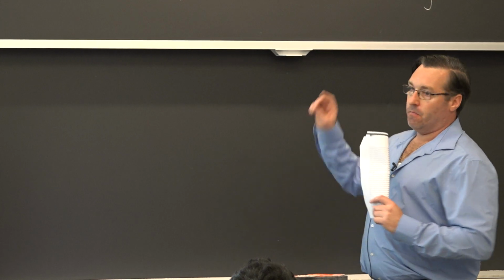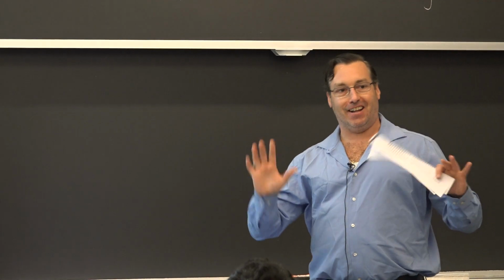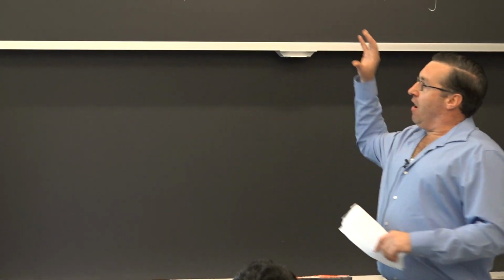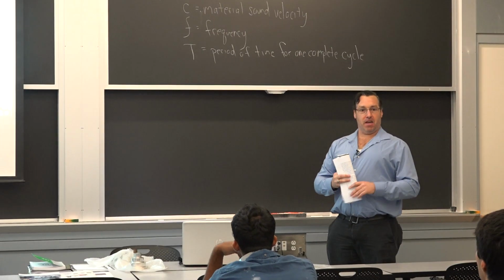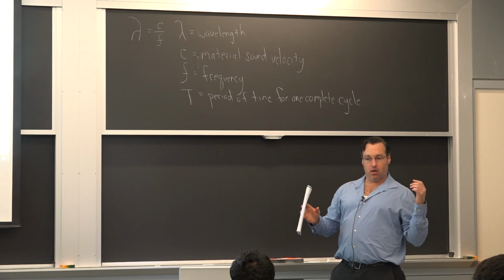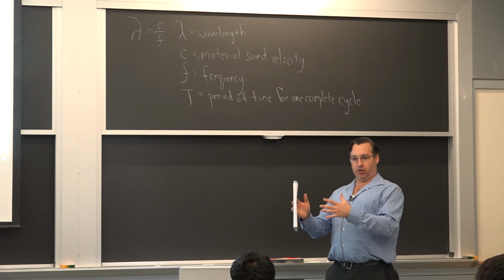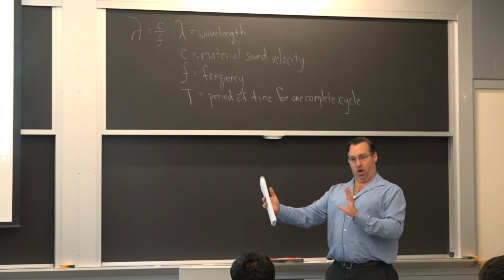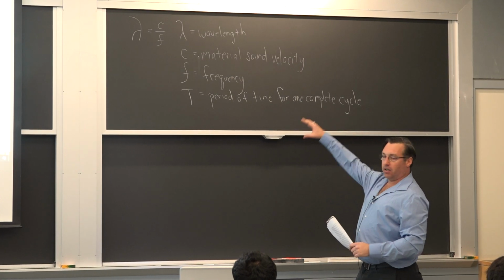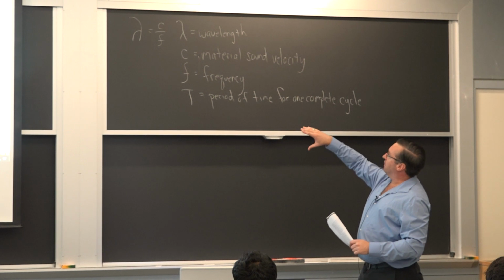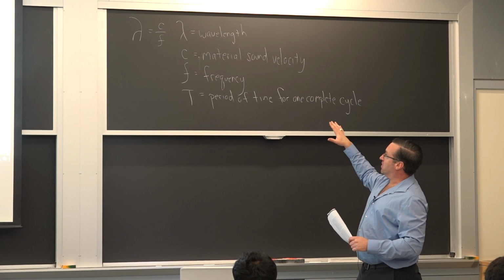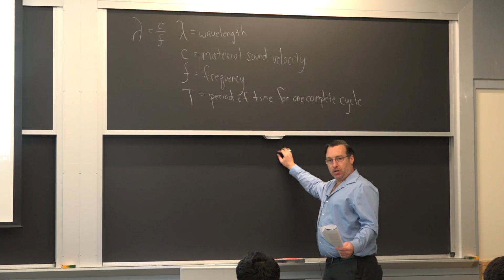So, I'm trying not to get too mathematically intense here, but we're talking about ultrasonics. The main thing, ultrasonics are typically used for when you have to penetrate into deeper samples, thickness-wise. The main equations are: wavelength equals the material sound velocity over the frequency. Very simple equations.